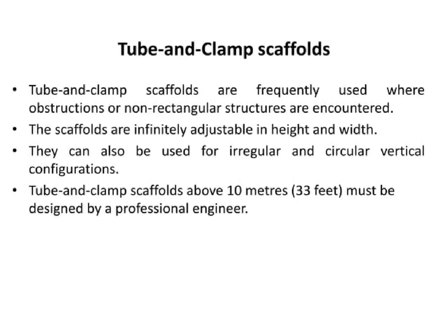Scaffolding on a non-rectangular structure can be erected using a tube and clamp scaffold, which is infinitely adjustable and can handle irregular and circular vertical configurations, as well as obstructed areas. However, for scaffolding higher than 10 meters, a certified engineer must design it to ensure it is safe and stable.